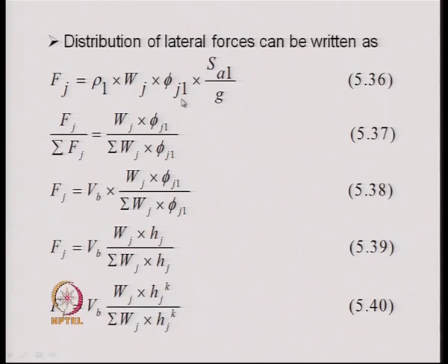corresponding to that there is a mode shape coefficient in the first mode, and that gets multiplied by SA1 by g, the spectral acceleration for the first mode, normalized with respect to g, so that it finally becomes mass times acceleration. W by g becomes the mass and mass times acceleration becomes the force.